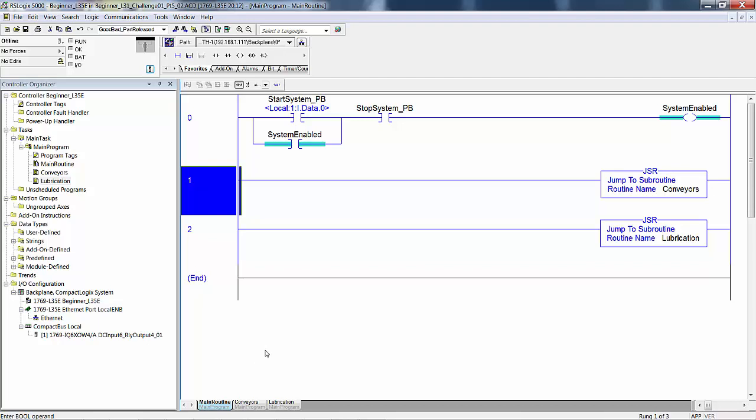We need 1 at the entrance of all 3 conveyors positioned to sense the leading edge of a part arriving and trailing edge leaving. We can use timers and counters for the remaining sense, so to speak. We would know how long the conveyors are and the surface speed of each conveyor belt, thereby being able to predict exactly where on the belt an object is. Now we're not going to go to that length in this particular challenge, but you could do that.